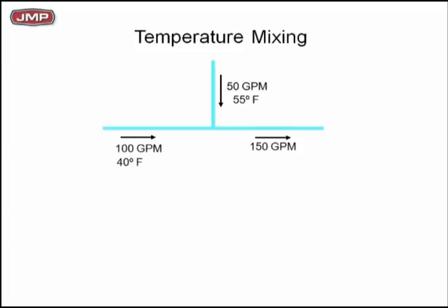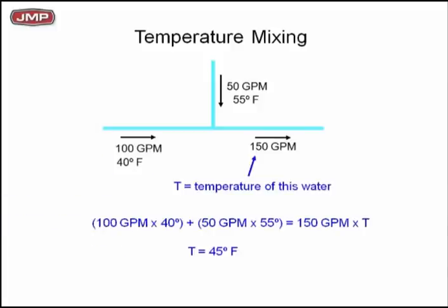So let's look a little bit at temperatures of these T's we talked about, because obviously if we have different flow rates, we're mixing flow and we're mixing temperature. So here's a simple little formula. We'll get it in front of you real quick. It's not complicated at all. If you know the flow rates in the T's and you know the temperatures, it's very easy to calculate the temperature leaving. This is probably the thing you need to spend a little time on, because with boilers for hot water or chillers for chilled water, you need to understand these blended temperatures and what happens.